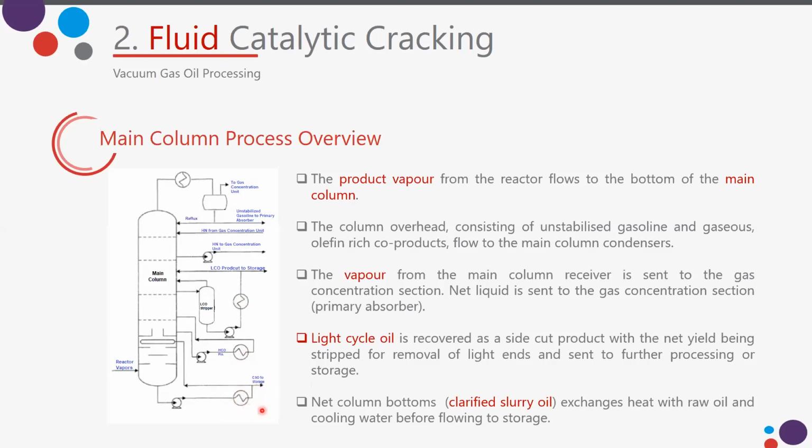Yeah, so we've got a question from Miss Hibe saying, what's the purpose of the reflux of the light cycle oil and the clarified slurry oil? So if you answer that one also. Yes, this is also to have the proper traffic inside the column. Like the pump arounds in the main distillation column.